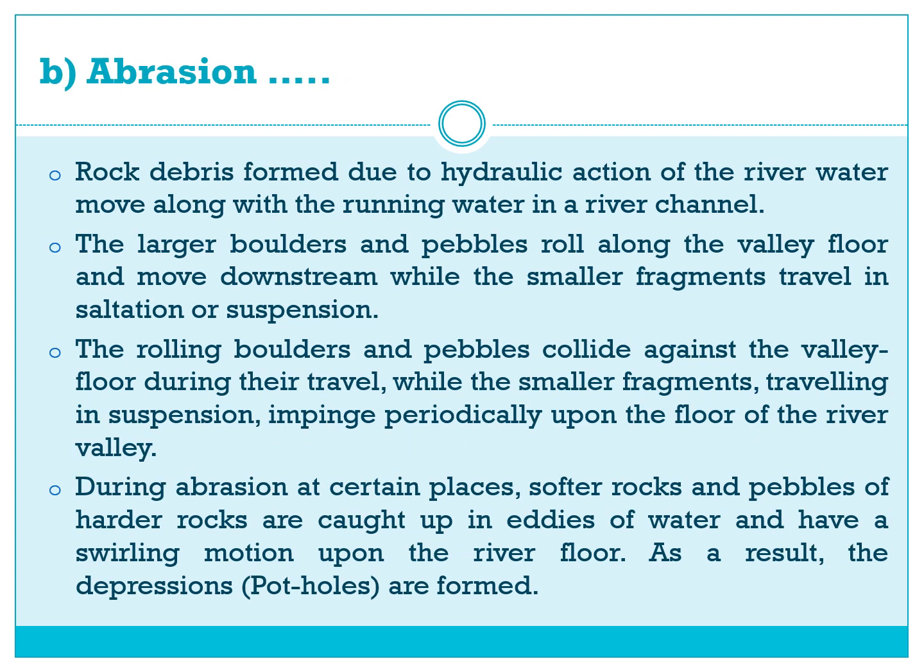Abrasion. Rock debris formed due to the hydraulic action of the river water moves along with the running water in a river channel. The larger boulders and pebbles roll along the valley floor and move downstream, while the smaller fragments travel in saltation or suspension. The rolling boulders and pebbles collide against the valley floor during their travel, while the smaller fragments traveling in suspension impinge periodically upon the floor of the river valley.